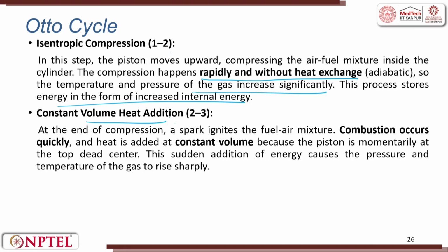Then comes constant volume heat addition. At the end of the compression, the spark ignites, because when you ignite it, it is a combustion, and there is a propagation of an explosive energy front. The spark ignites the fuel-air mixture and the combustion occurs quickly, almost instantly. The heat is added at a constant volume, because the piston is momentarily at the top dead center. This sudden addition of energy causes the pressure and temperature of the gas to rise sharply.